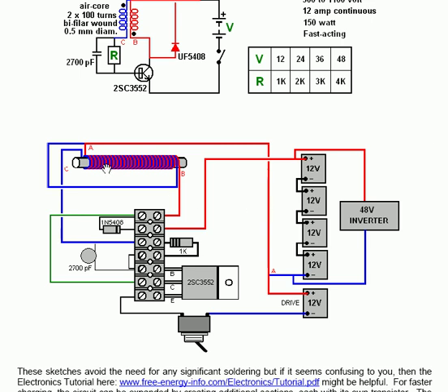You've got red, blue, red, blue, red, blue all the way through the coil, and then 2 of the wires are connected together. The end of one wire is connected to the start of the other wire, and this forms a bifilar coil, which is very useful and very effective. Designed by Tesla, it is one of the most effective coils around. But the arrangement here can be set up quite readily.